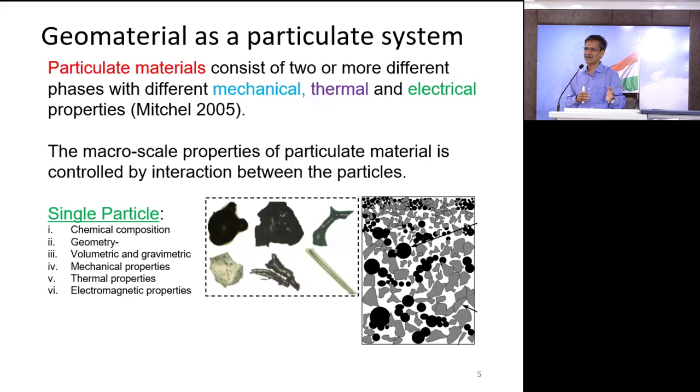Which will affect it, which you will not be able to identify if you consider it as pure geotechnical engineering. Because I know the moisture content, OMC is 13%, plastic limit, liquid limit, so I can find out the properties. But in this case, water content is not sufficient to know about volumetric. So we have both volumetric and gravimetric. We should know volume by volume. So that will make a difference.